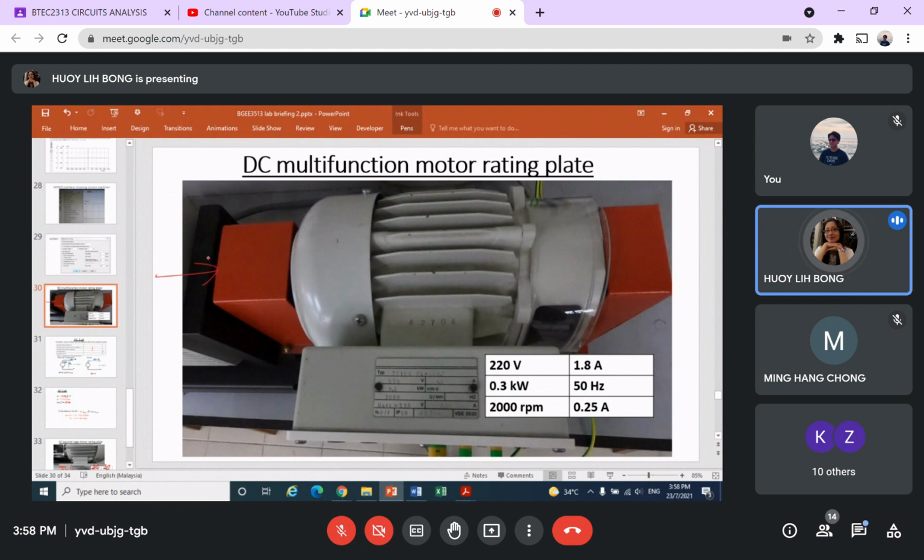It's using the machine test system, so we can only control the torque here, either increase or decrease it. By controlling the torque, we get the power output, which is torque times speed over 9.55. The speed is uncontrollable, so we can only control this. We want to see how much to input in order to get this power.